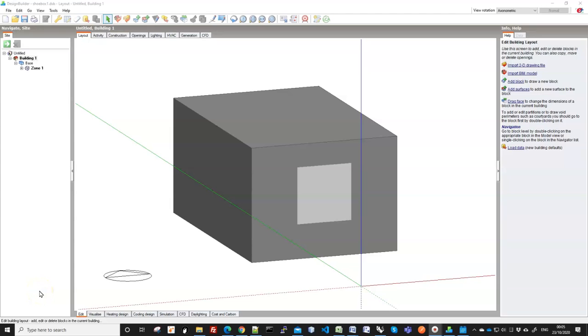We have looked at how to use DesignBuilder's parametric analysis tool. Now, if we want a little more power, for example, to have more than 2 parameters, and to process and plot data our own way, we can use the EnergyPlus model directly.